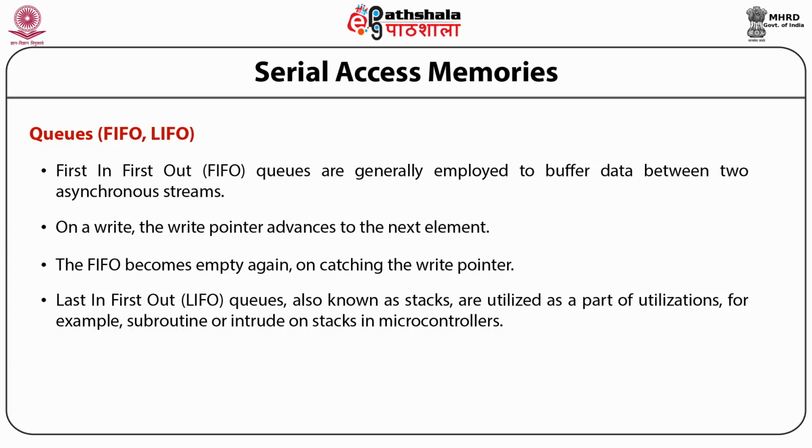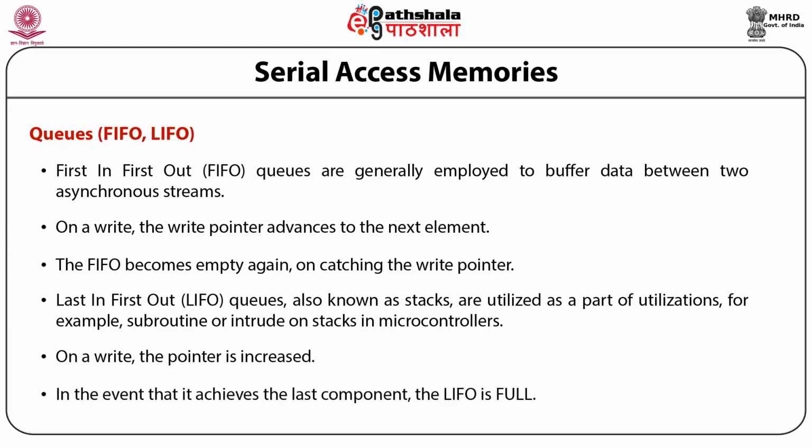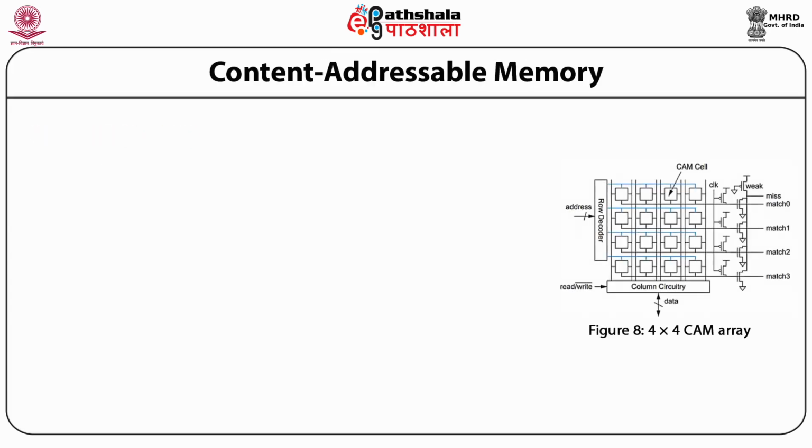On reset, the pointer is initialized to the first element and the LIFO is empty. On a write, the pointer is incremented, and if it reaches the last element, the LIFO is full.